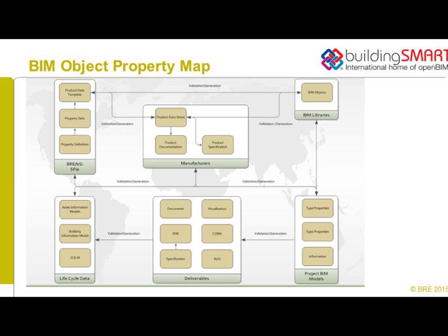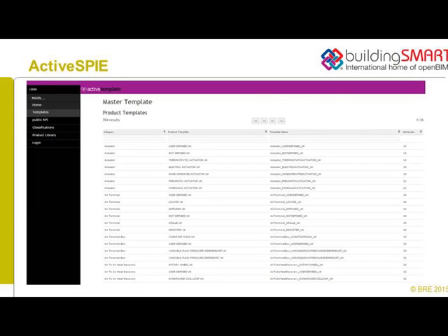Okay, so really we're looking at object naming, attribute naming, shape naming, sorting out this property information exchange on objects. Then we're going to populate those with product data templates produced by CIBSE, MDS, and all the other people. Obviously the whole tie-in is buildingSMART, IFC, COBie. Those are the standards that we look after. And we're also tying in what's going on with the digital plan of work and other things that are happening. The whole idea is that if this is going to work for level 3, we've got to sort out this whole big data thing and get everybody calling the right things the right names.